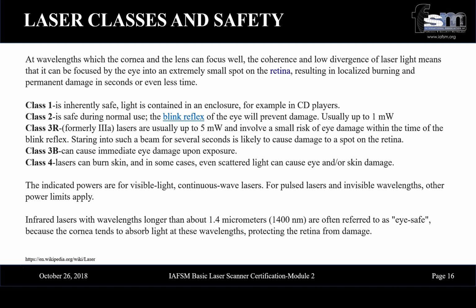Now, it's interesting that the laser scanner rotates around, as many of us know. So it isn't like, for example, a total station. A total station, for any of you who are familiar with it, you point at an object and then you fire a shot. And when it fires a shot, the total station isn't moving. It's actually taking a number of measurements with a still standing wave, just like a laser pointer would be pointing at an object. So in any condition, I think it's safe to say that we don't want to be staring at these units or trying to put yourself close and staring into the mirror or the components of any laser device. And I think that just makes sense.